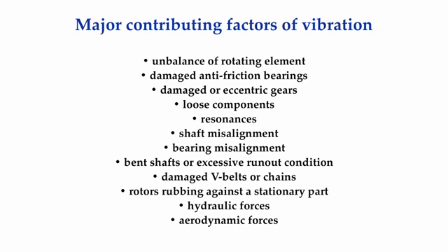These are very serious problems that can be identified through vibration analysis. Vibration analysis is the best non-destructive test you can perform on a running piece of rotating machinery to determine the damaging dynamic forces that are present. If you have rotating machinery in your facility and are not doing vibration analysis, I strongly recommend that you start. Otherwise, you will not have the ability to determine the possible source of your vibration problem and will only be guessing what's the matter when one of your machines starts going into tilt mode.